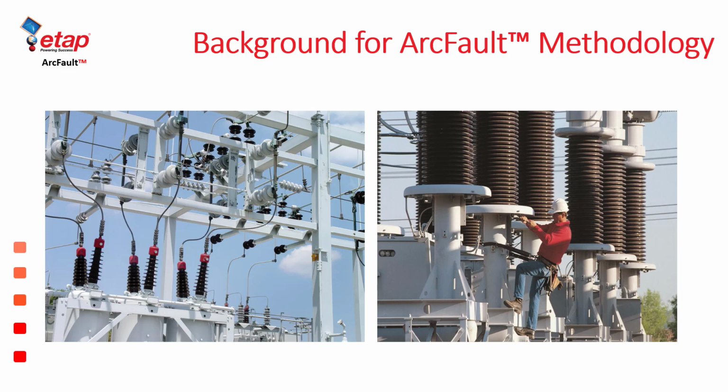One thing that you should note in this particular slide is the potential distance between ground and the phase conductor, and the potential for an arc fault to occur between these 2 points, which will be the most likely point of occurrence for an arc fault. Of course, another distance which could be observed for a less likely occurrence of an arc could be the line to line distance.